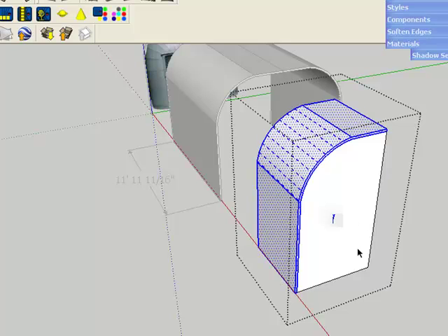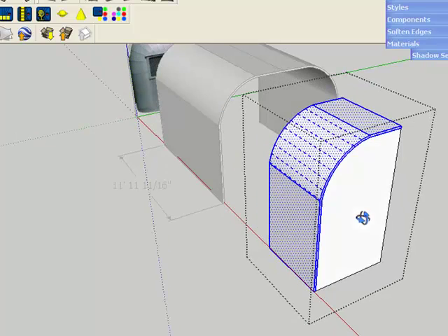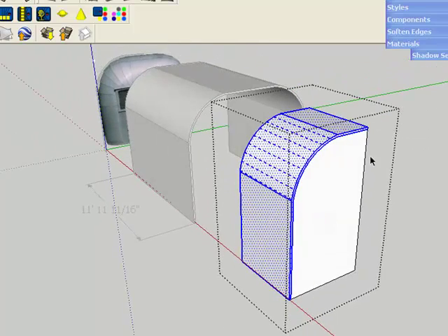Now if either one of these lines is not perpendicular or straight with our other design, the box won't show up. And so it meant that you got either one of these lines slightly out of order. So if you draw your box and you don't get it filled in, go back and review this part several times till you see what needs to happen. Alright, so we have our front cap started. We have the end filled in.